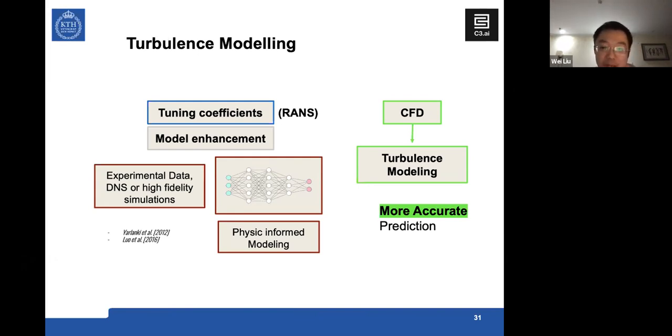Therefore, RANS turbulence models are not universally capable for every flow, but actually depend on the specific flow features. So for a complex flow with multiple characteristics, choosing standard values is a compromise. A first obvious way to utilize deep learning algorithms on the turbulence model is for constant tuning, finding for different flow applications the best values of the coefficients of a particular turbulence model. Such a method is not very generalizable though, and could possibly increase the uncertainties.